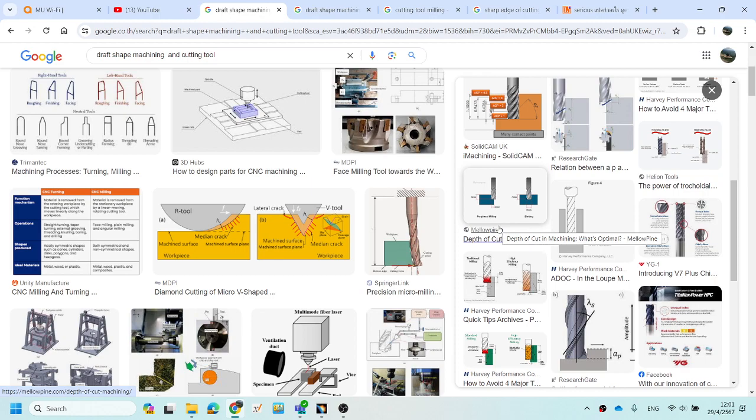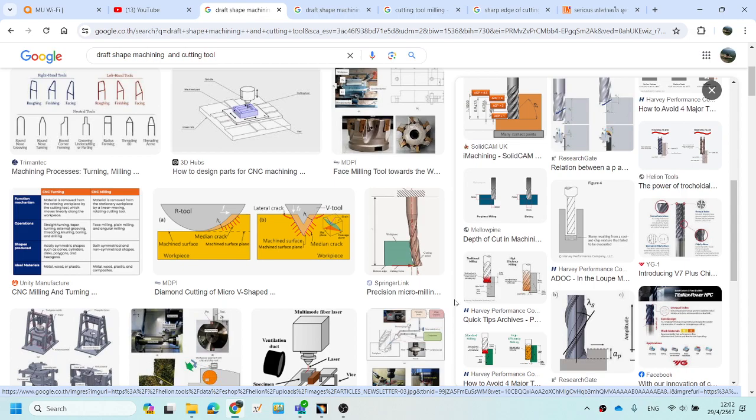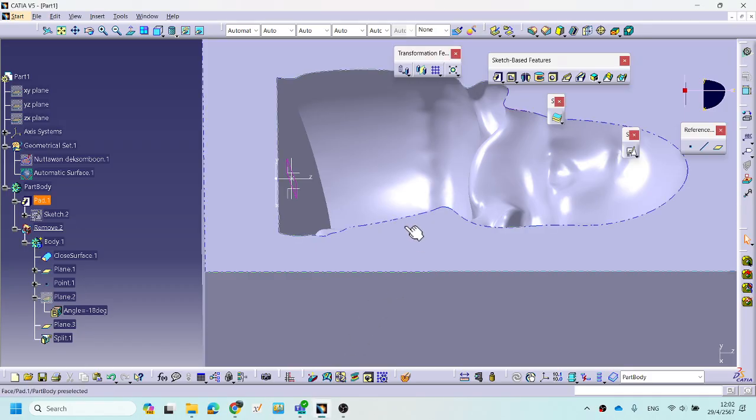If the cutting tool touches the workpiece over the area, you make a lot of force from the cutting tool onto the workpiece, right? With a lot of force, the cutting tool may break more easily. You avoid that by using the draft angle, like this.